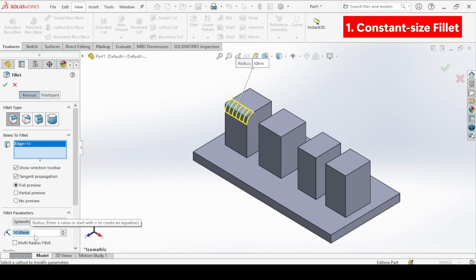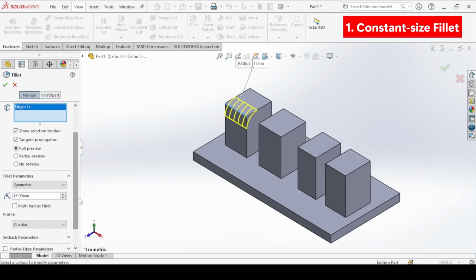Go with 20 millimeters or 15 millimeters. And you can see the radius of this fillet will be 15 millimeters. You can do this, or we can select a multi-radius fillet. Now, any other edge you select, let's see, this edge, will all have a radius of 15 millimeters.